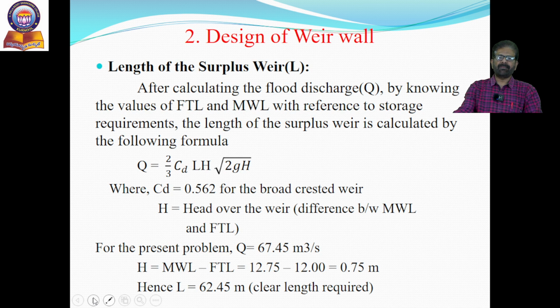Generally, in any hydraulic structure, these walls, as retaining walls, are trapezoidal in shape. From the stability and safety point of view, the ideal section is the trapezoidal section, since it has more stability. So always we should recommend the wall or structure in the form of a trapezoidal cross section.